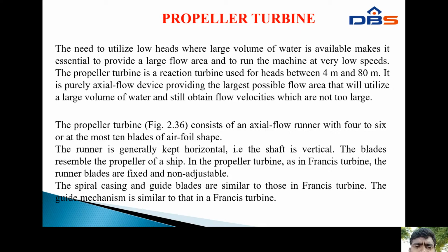The propeller turbine is a reaction turbine used for heads between 4 meters and 80 meters. This is a low speed, low head turbine.